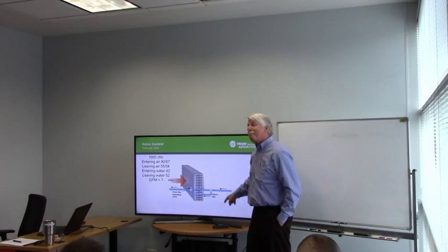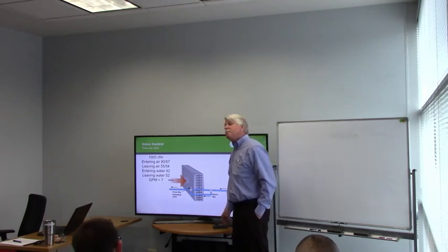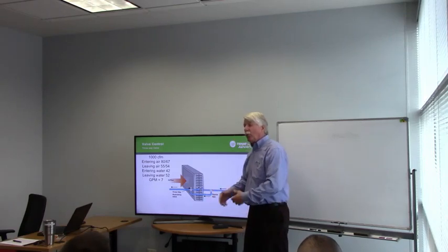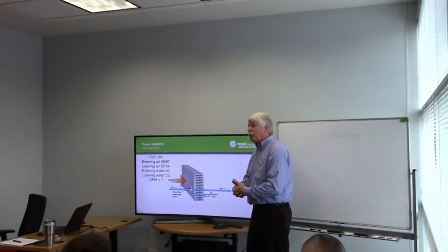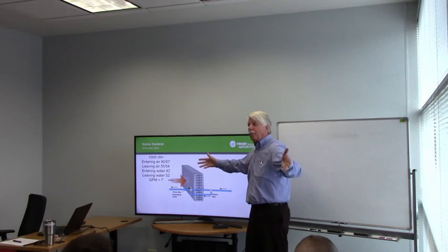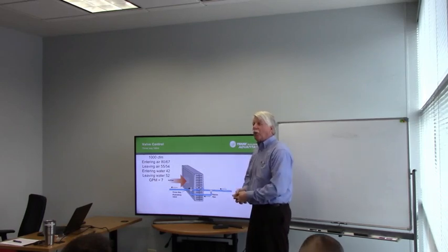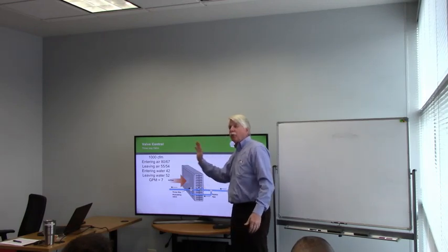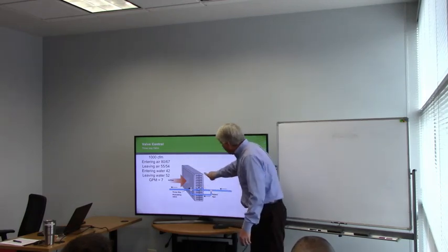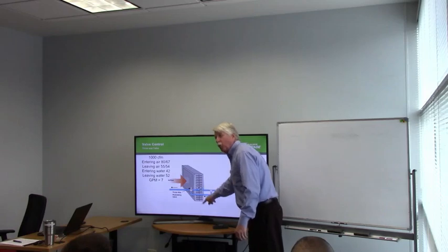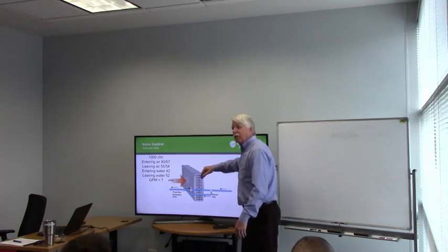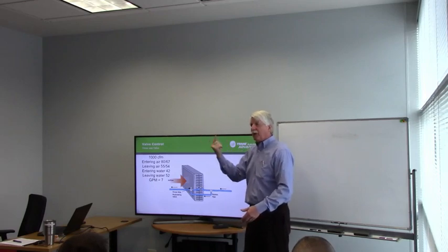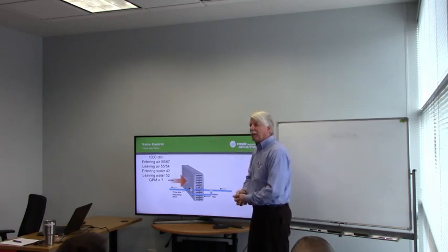Does it matter, Tony, if it's a double row or a single row coil? No, no. It can be anywhere from a 1-row coil to a 10-row coil. Now typically on chilled water coils, each pass is 1 row. In other words, they'll feed all the tubes on 1 row, send the water down, and on the back end of the coil, there'll be U-bends that turn the water around and bring it back.